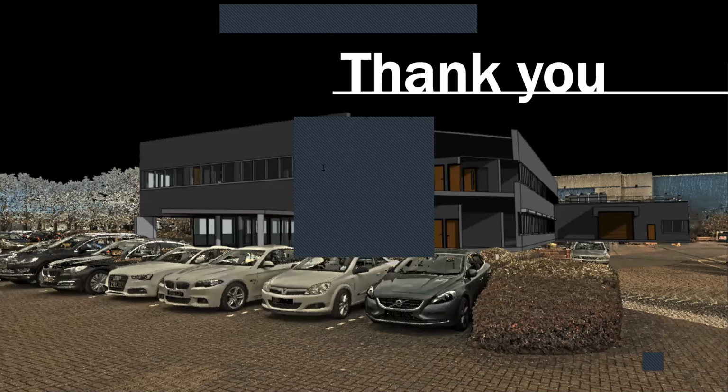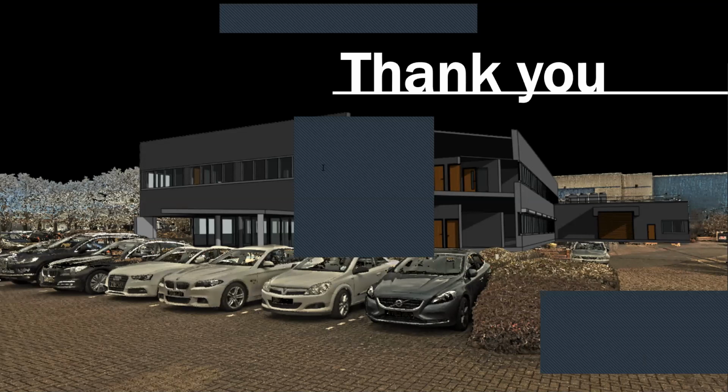Okay. In this, the thing is, scanners are handheld devices. Those are free to move. So you can just go on a site, put it on a tripod like a total station. This is basically like a total station. The difference is a total station captures 1 point per second and you have to manually operate it. A 3D laser scanner captures 360 degrees with 1 million to 2 million points per second with the same accuracy, and you can install it anywhere on the site. So it doesn't have a particular location.